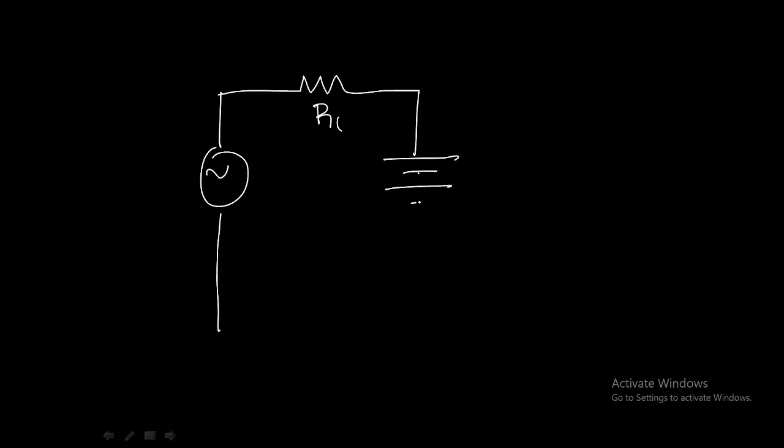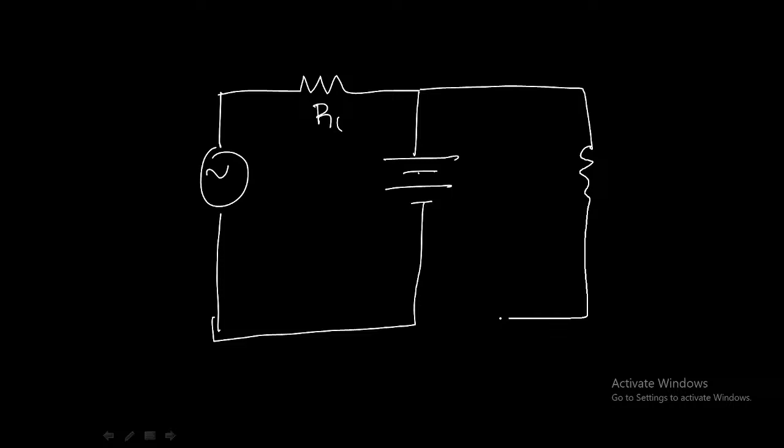So when we have approximated our diode model, this is R1. It will act as a voltage source of 0.7 volts when the diode is in forward bias condition. This is RL. So this is 0.7 volts. Here you have 0.7 volts, then at the resistance RL, the output voltage is 0.7 volts only. So how much you increase the input voltage? I will draw the waveform also.